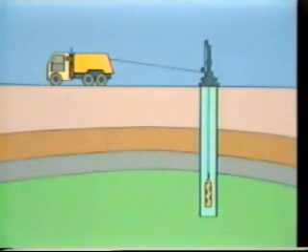Perforating can be carried out in several different ways. Conventional overbalanced perforating is done through casing with an electrical conductor line and a heavy fluid in the hole, which creates hydrostatic pressure greater than the formation pressure.